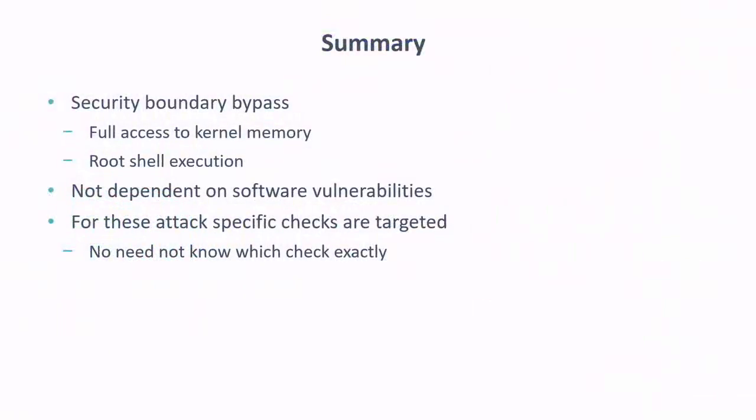It's important to realize that this kind of attack focuses on a specific point in time, on targets where there is a check, and you want to shoot at it in order to see if you can actually change that behavior. This has been a very widely used attack, also during secure boot, also in academia. If you have a check at some point, you might want to duplicate it so that I need to shoot at 2 checks. So it is more difficult.